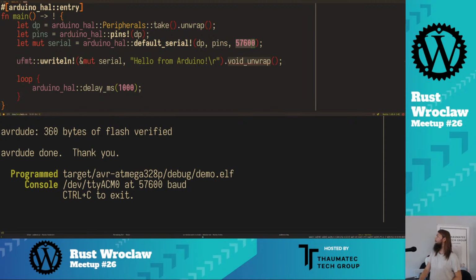and this third integer tells the speed of the UART. So we'll stick with the defaults, but just if you're curious what this integer means, it's the bits per second, how fast you want to travel through UART. Because I think there is no negotiation algorithm, so if you want to connect two devices through this UART protocol, they have to agree on the speed. So in this case, I know it's hard-coded on my computer side to be this 57,600. If I changed it, I would also need to change it in my computer's template. So we'll stick with the default.